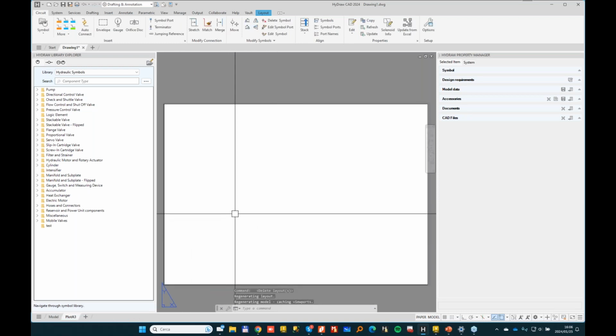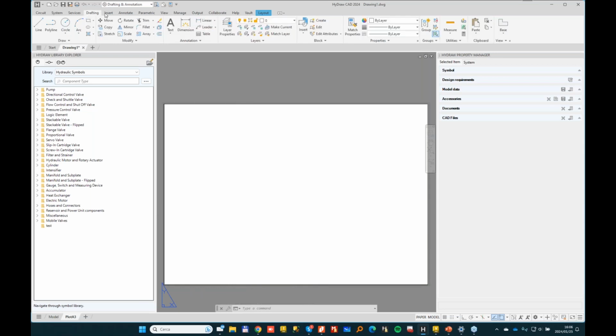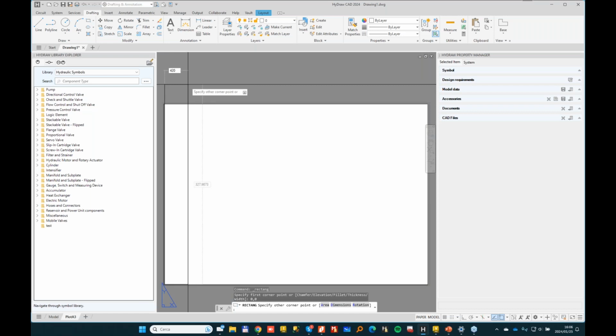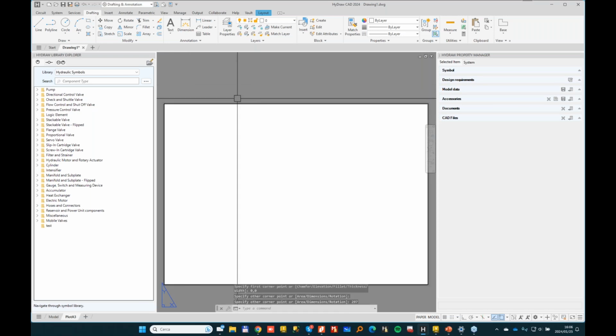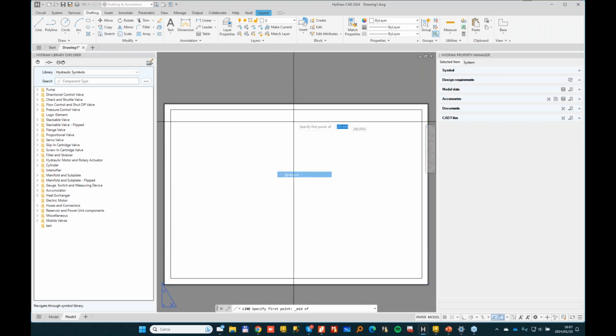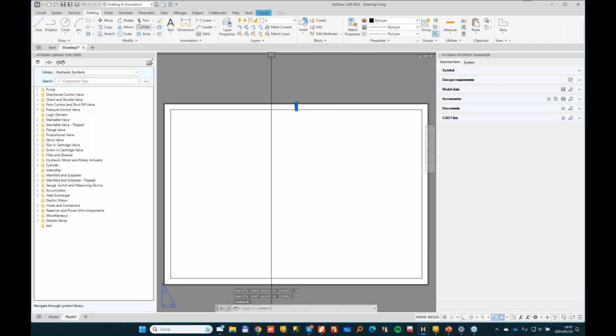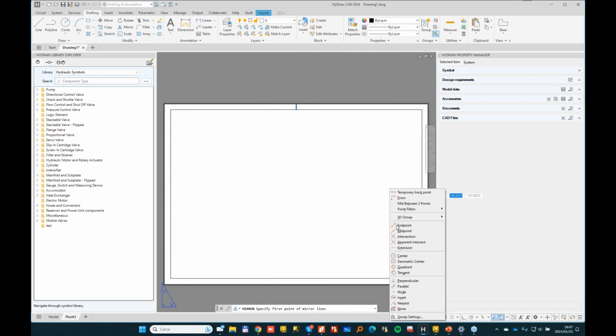In my A3 page, I want a frame, so I'll just draw a rectangle, drafting rectangle, starting from 0, 0 up to 420, 297, which is an A3. I also want another frame. Let me do offset 10 millimeter from this rectangle. And then if you want, you can add the midpoint. So 10 millimeter. And we can use mirror commands to mirror entities.